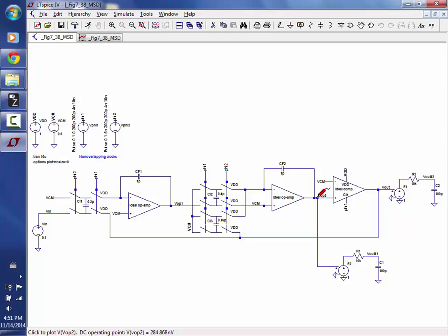And so there's situations where we're taking a complicated signal here and we're trying to dumb it down to a simple little, oh, the gain's 0.25, so we can get some idea on how to select the capacitors. But it does not mean that the system's going to stay stable, because it's changing. It's a digital system. It's changing from one clock cycle to the next.